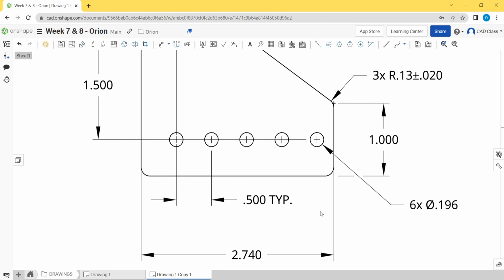That's all within tolerance. But basically what that means is I've got 4 gaps that are each 3 thou over. That means that this hole is actually 12 thousandths of an inch farther away from this hole than it would be if all the spacings were spot on 0.500. So that's something to keep in mind, and that's what's called tolerance stack up, which is when I have dimensions or components that have individual tolerances, and those tolerances are chained in a line.